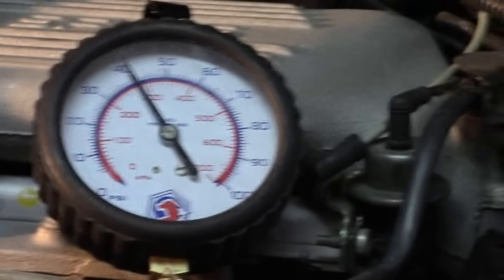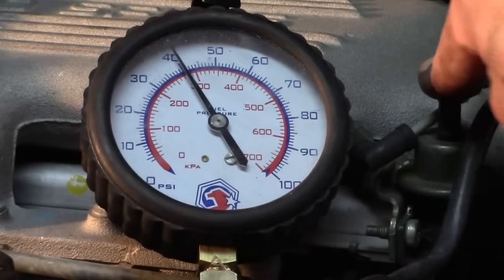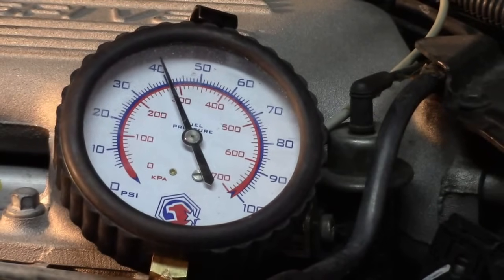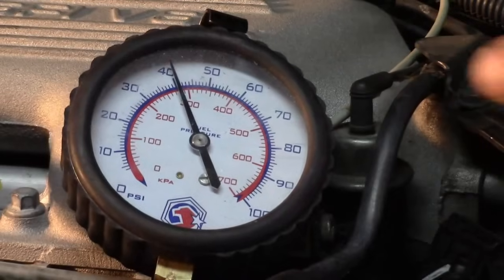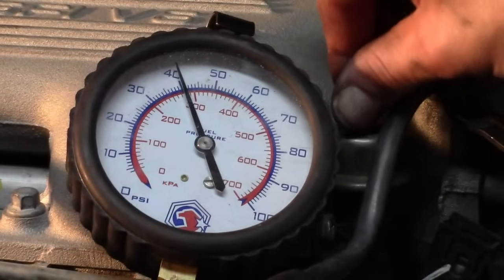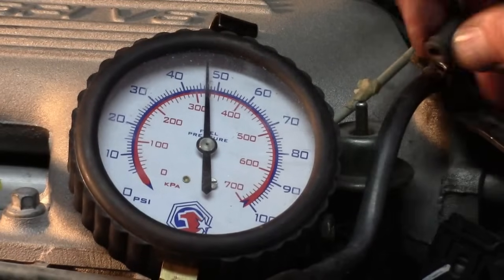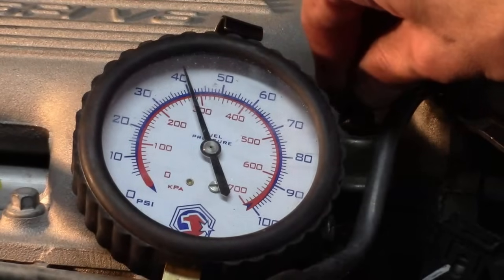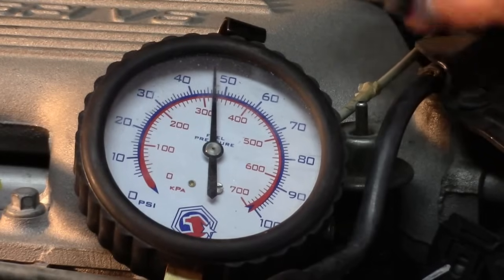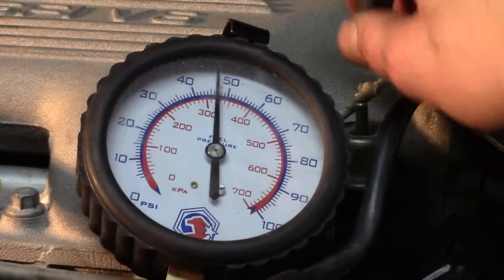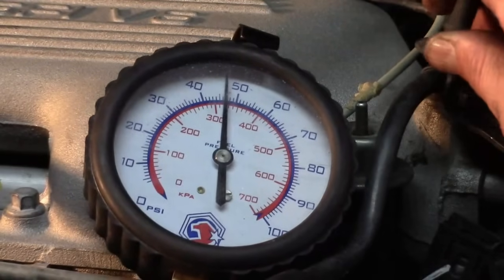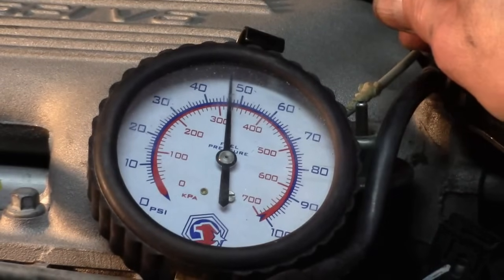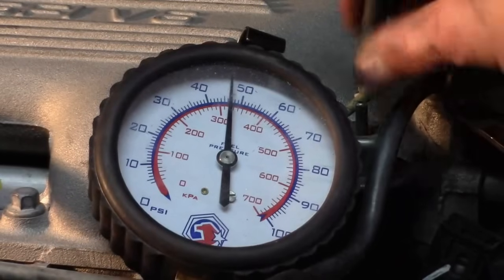Now, let's go ahead and see what is going to happen when I remove the hose from my fuel pressure regulator. Well, we know what should happen. The regulator is actually open right now because of the engine vacuum through the hose. So we should see a pretty good increase in fuel pressure if I pull this off. And we see we do. It's back to almost the priming pressure. That's why the pressure dropped when we started the engine, because we added vacuum to it. So right now, we also, of course, have a vacuum leak here, so I'm just going to plug that with my thumb right now. But you can see that the increase in pressure is due to the fact that we've removed vacuum, which is the same thing that would happen, as I said, when you would apply throttle.